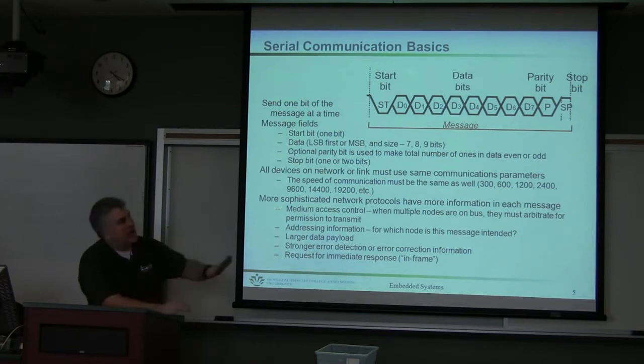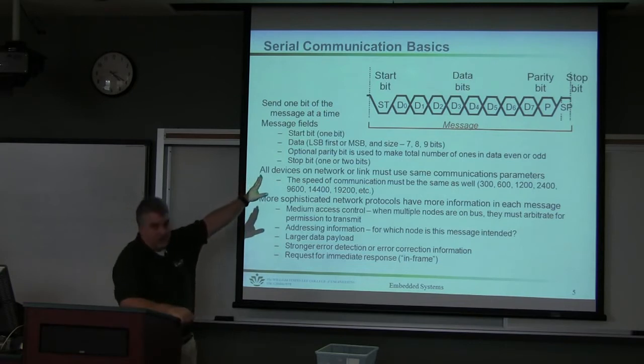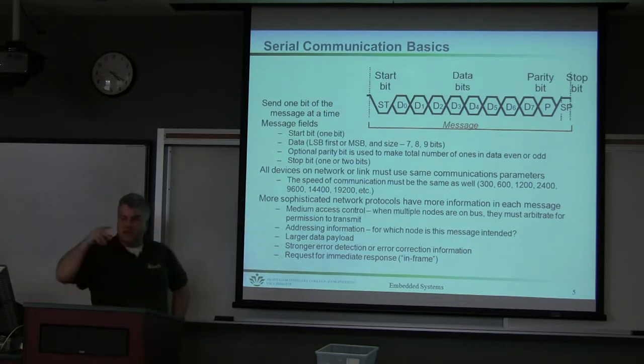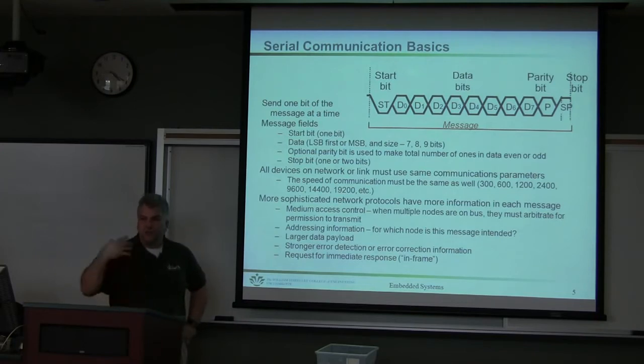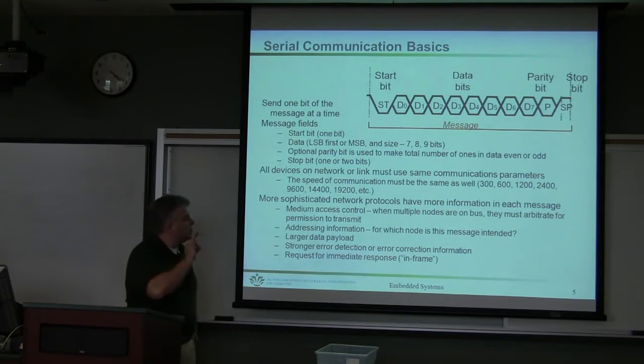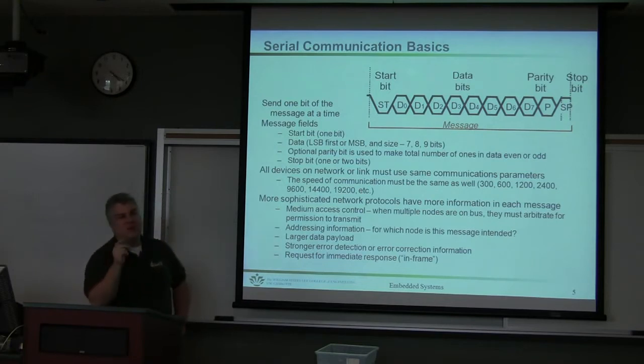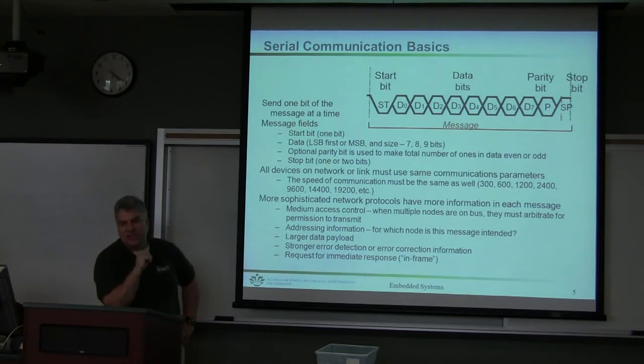So what communications designers do is they send a start bit that says, all right, now start your timing. We agreed on a certain speed, and I'm going to be sending a certain number of bits. By the way, it also pads it at the end with a parity bit, which allows you to check things.